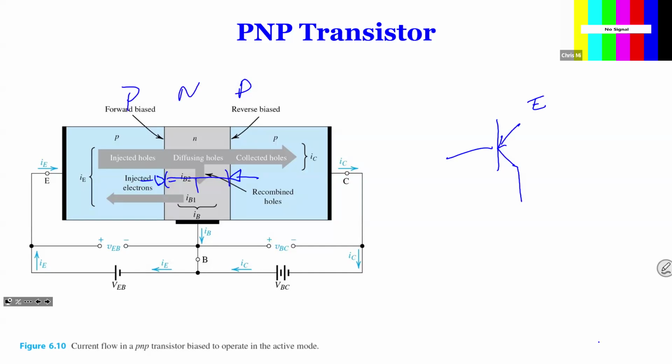And we have the emitter on the top, and then we have a collector at the bottom, and the base over here. So the symbols now, everything is like a flip. Instead of VCE, we call it VEC. Instead of VBE, we call it VEB, right? And then the current up is IC and IE.